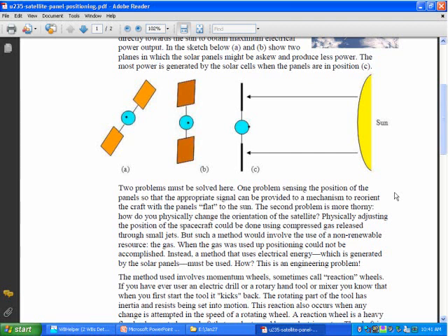And the extra one may be used to store energy. That is, it's a form of battery. The cells are generating electricity here and now. If you don't have to consume the electricity now, you want to save it. Well, how do you save energy? In a battery, batteries are kind of heavy. If you have this 4th momentum wheel, you can store energy by speeding it up. And then you can recapture the energy by having it drive some generator to get it back, maybe when the satellite's rotated around the other end of the Earth and the sun isn't around and it can't generate electricity for itself. So pretty clever engineering in satellites.